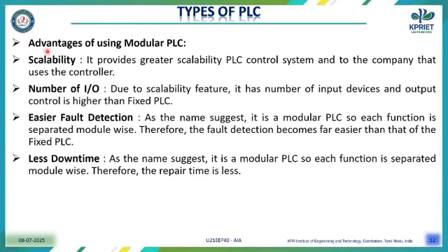What are the advantages or benefits of modular PLC? The first one is scalability. It provides greater scalability to the PLC control system and to the company that uses the controller. Due to the scalability feature, the number of input devices and output control is higher than the fixed PLC.